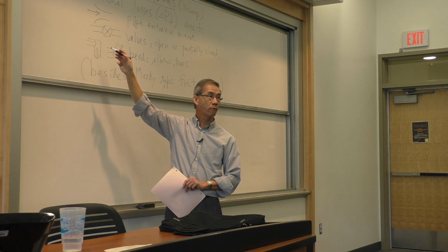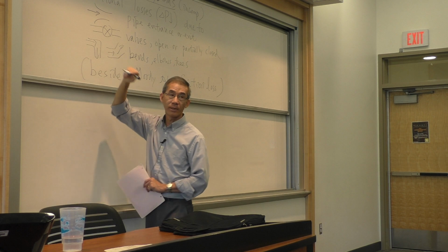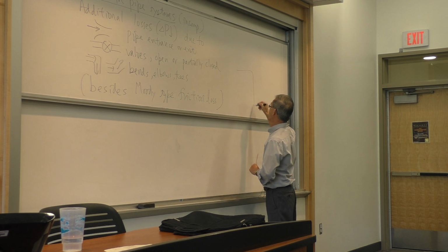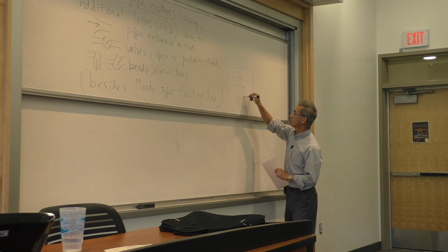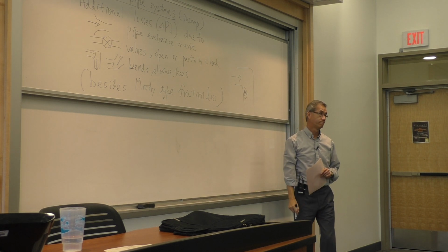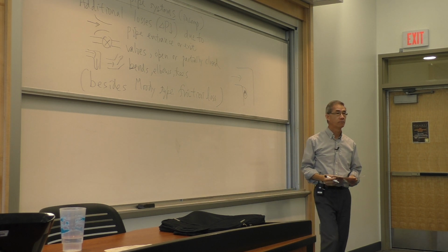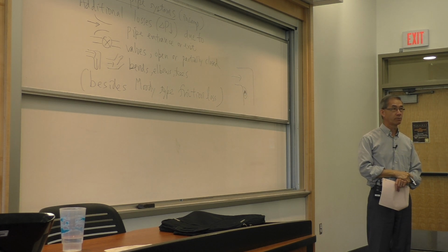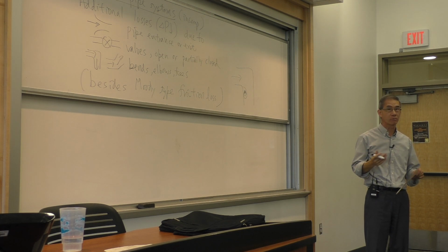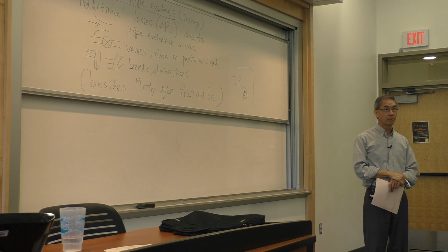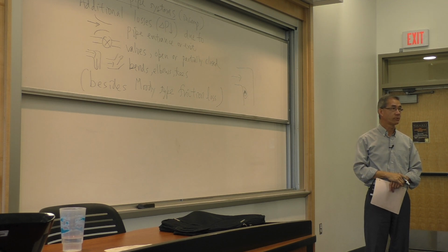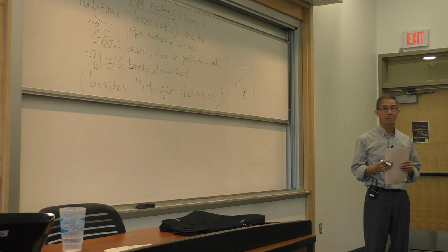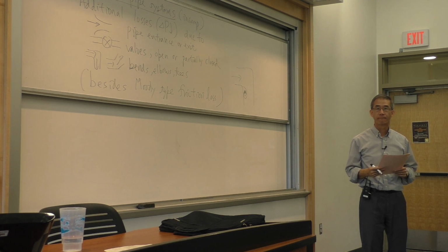And when there's friction involved, the fluid cannot follow that 90-degree turn. So if I look at some of the detail, the flow comes in around this corner, and the flow will separate. That separation is what creates losses, not purely due to shear, not purely due to friction, but due to the fact the fluid doesn't want to follow the contour. Okay? So that is the kind of losses that we are now tackling, not purely due to shear and friction, but other flow mechanisms. Yes? How do you distinguish between minor and major losses?